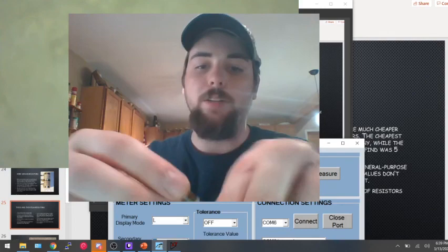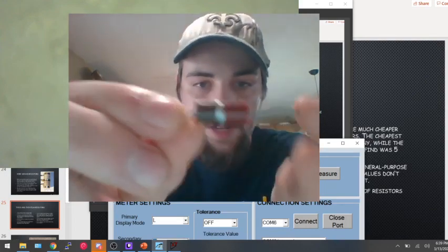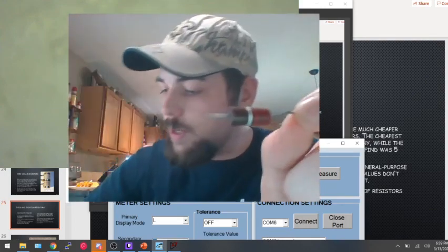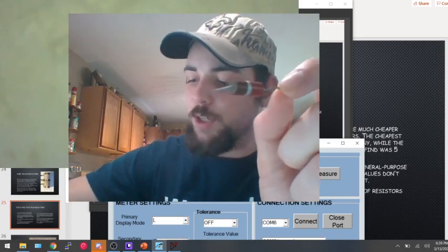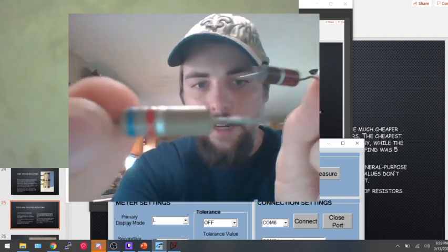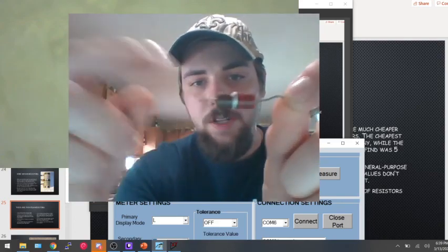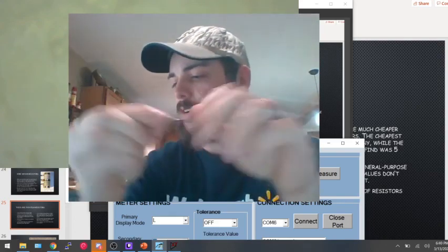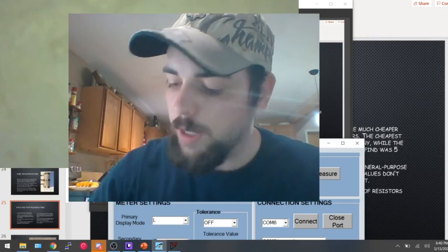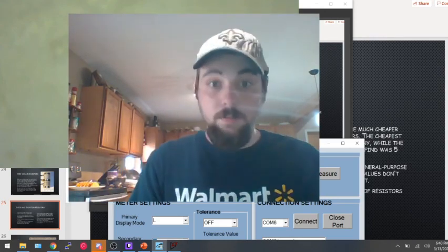It's known as an Allen-Bradley because you can see that it's got a squared off end. This one right here is also carbon composition, but it's kind of got a weird pitted coating and it's rounded, right? So these ones I'll get to in a second. They're not so good for stability, but they're low inductance.